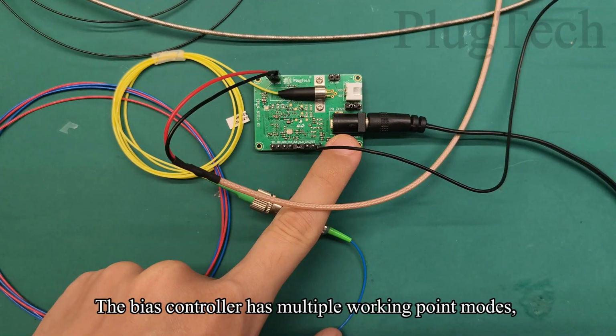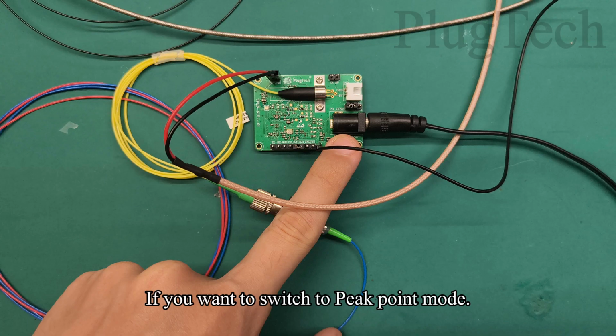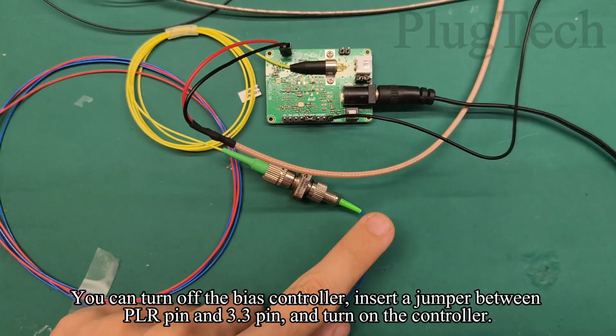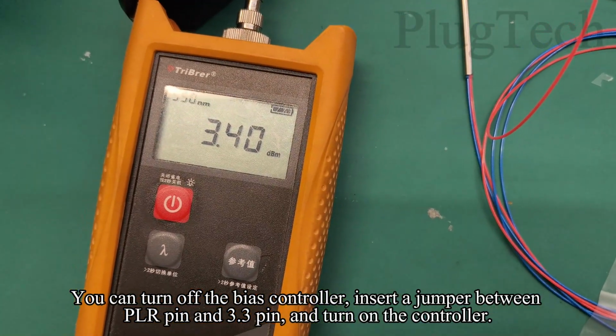The bias controller has multiple working point modes. The controller is working in null point tracking mode by default. If you want to switch to peak point mode, you can turn off the bias controller, insert a jumper between the PLR pin and the 3.3 pin, and turn on the controller.